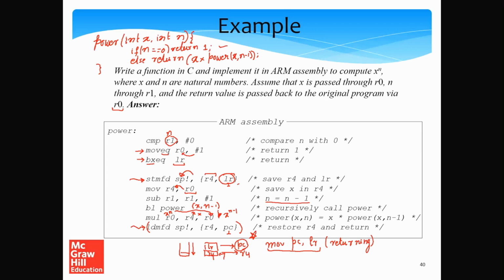This little piece of code, if you take a look at it, this C code has essentially two statements inside it. In terms of assembly code, it's actually fairly complicated. It turns into 3, 4, 5, 6, 7, 8, 9 statements. But actually it could have been much more. We reduced it by using tricks in the ARM ISA. One trick that we used is the EQ suffix, the EQ condition, to ensure there are no branches, and we put in a predicated instruction there. That took care of the base case.